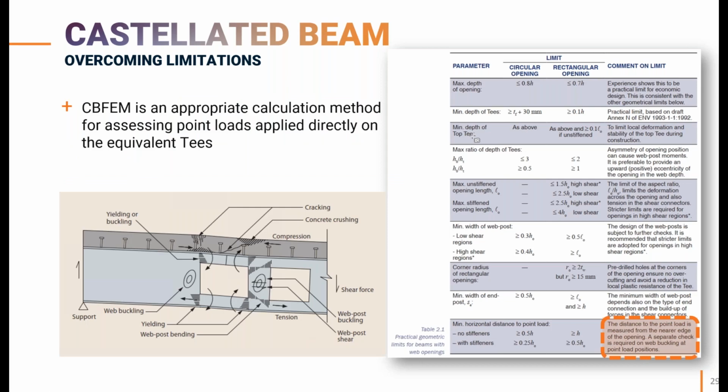Another limitation that is very important is that point loads should always be applied at a distance from the opening edges. This makes perfect sense, as concentrated loads create a local effect on the top equivalent T. This local effect disturbs the flow of stresses according to the theory.